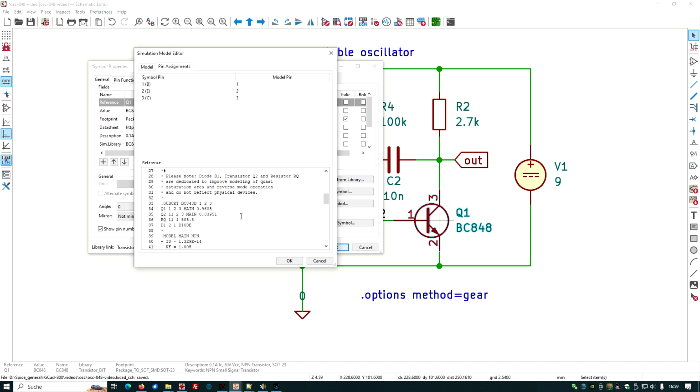They don't tell us. But you see, if this is the main transistor directly connected to the input, and it has collector, base, emitter, because this is a SPICE transistor, then we know that is collector 1, base 2, emitter 3. Okay, so what is collector? Collector is to become 1. Emitter is to become 3. And base is to become 2. And hopefully that's it.